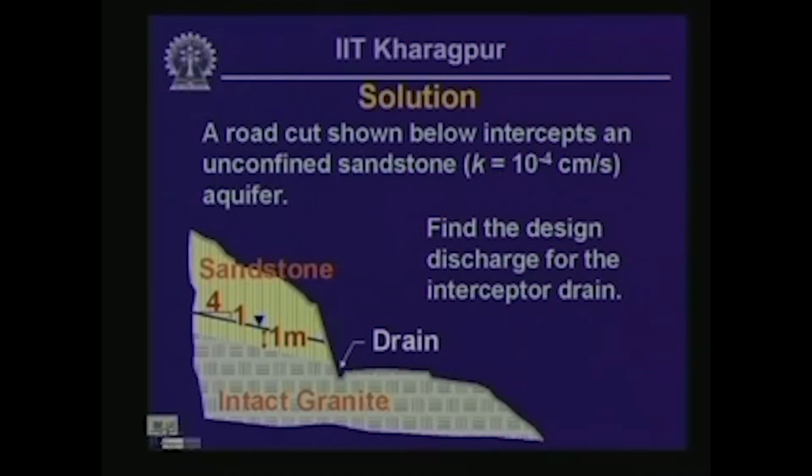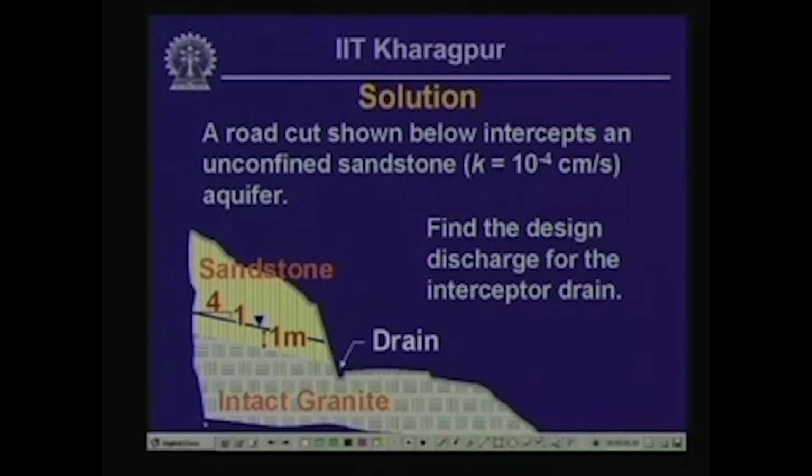Okay, now let's get on with the solution first. In this particular configuration, the hydraulic gradient is equal to the amount of head loss over the length of flow, and this will be the same in this case as the slope of the top of the water table.